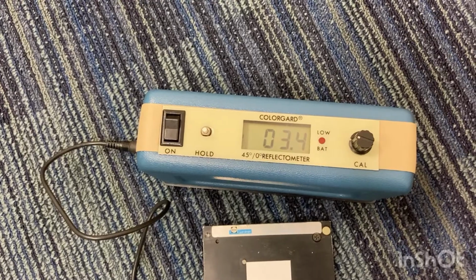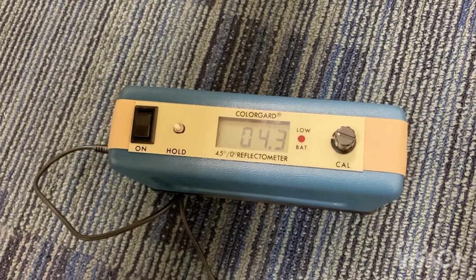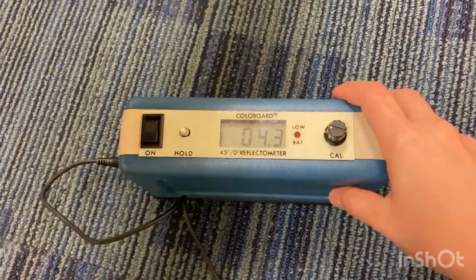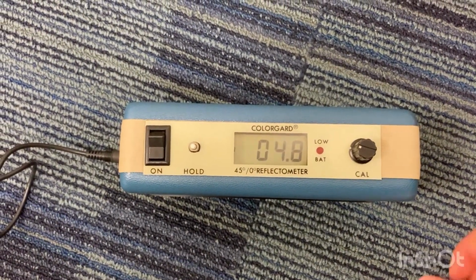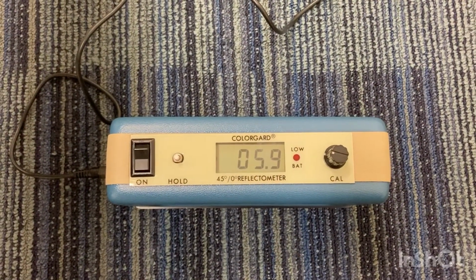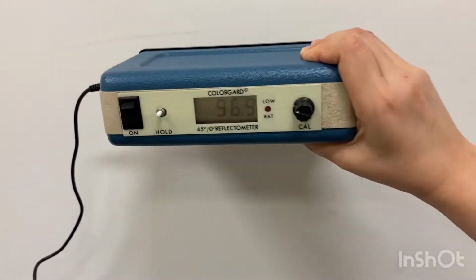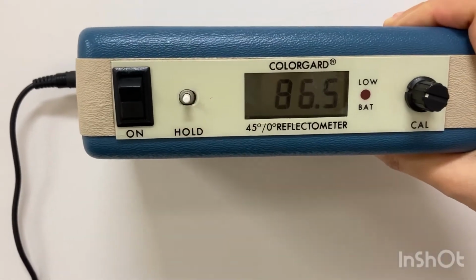Then we can use the reflectometer to measure the surface reflectance. You should measure many points and then take an average value. So in this demonstration, I have measured a few points, and after taking the videos, I measure some more points for other area of the floor. Next is to measure the reflectance of the walls. Once again, you should measure many more points and take an average value.